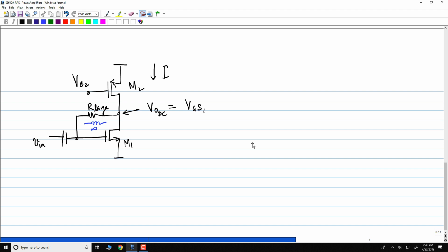So what I have to do is use common mode feedback to set it separately. This is also feedback, DC feedback, except I'm doing it through a resistor. Now I'll have to explicitly do it using an op amp.